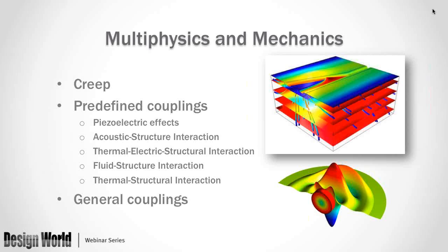A lot of care has to be taken at the boundaries where you want the pressure gradient to be proportional to the strain on those boundaries. So we've taken care of that for you with the acoustic structure interaction. Thermoelectric structure interaction, I think thermal actuators are the obvious thing here. When you pass a current through a conductor, there'll be a little bit of structural change, and this is especially important for the MEMS field.